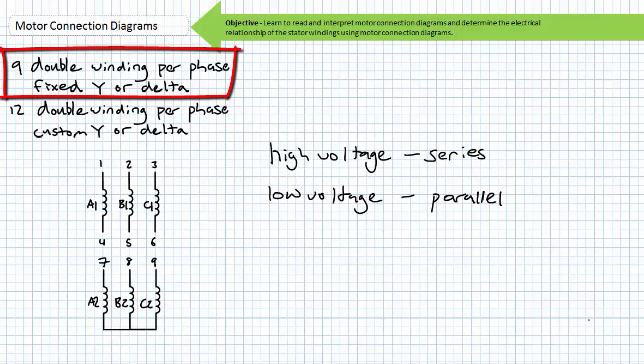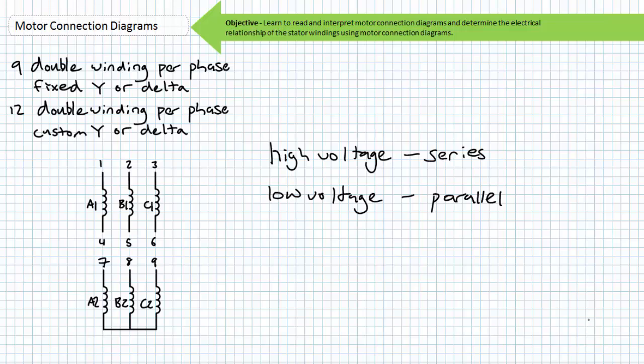9-lead motors are essentially an extension of 3-lead motors, in that a technician does not have a choice over Y or delta configurations. These motors typically feature windings pre-wired in a Y or a partial delta. The remaining leads can be wired in series or parallel with the pre-wired Y or partial deltas to allow connection to a high or low voltage source.